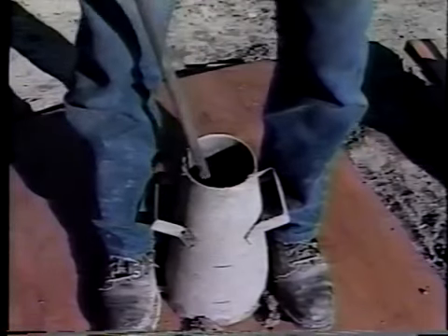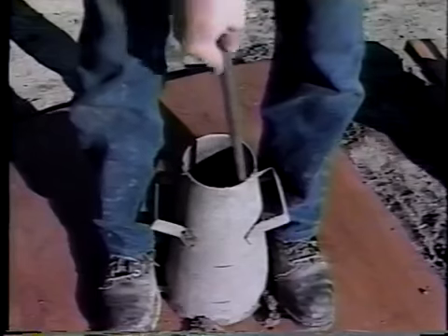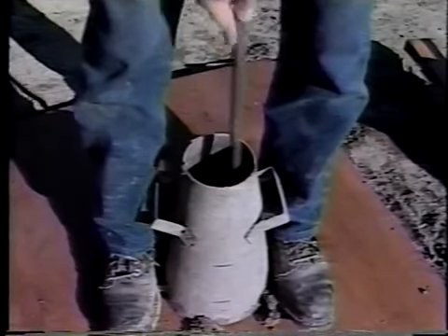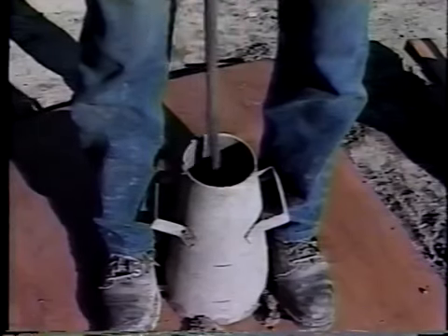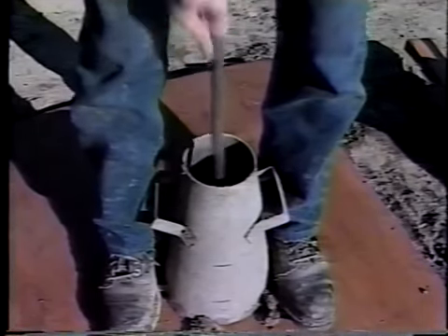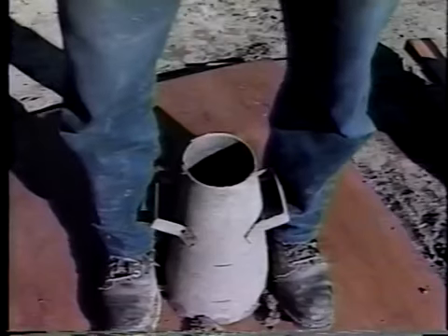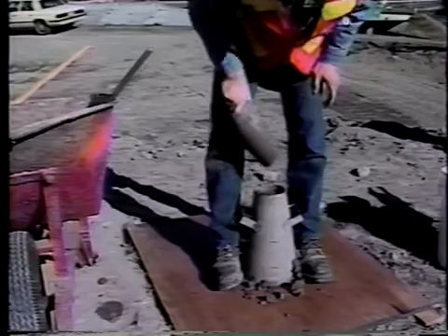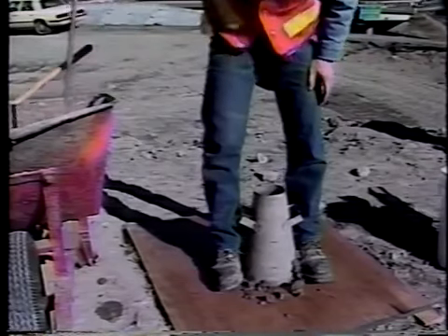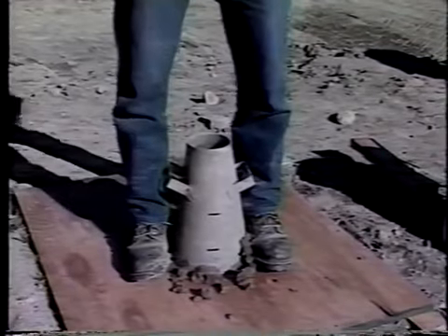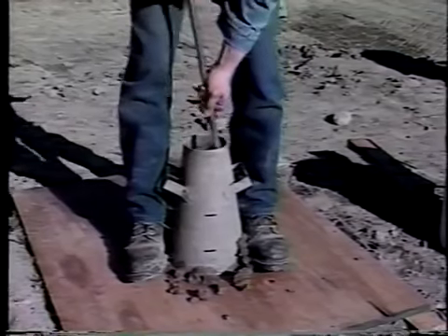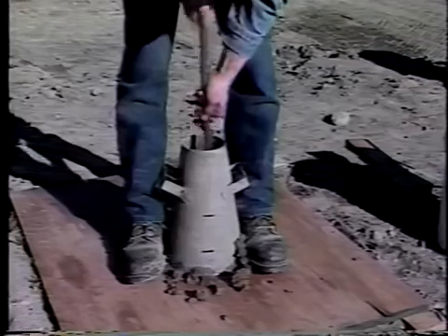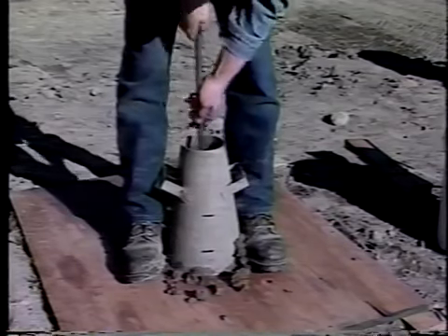A spiraling pattern should be followed as the rod moves toward the center of the cone. The strokes are distributed uniformly. As the rod is moved away from the perimeter, it's returned to the vertical. The second layer fills about half of the cone's height. It's rodded the same as the first, with one difference. The rodding should just penetrate about a ½ inch into the first layer, not all the way down to the base.